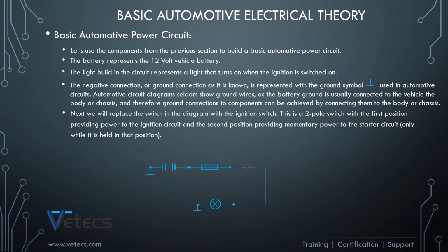Next, we will replace the switch in the diagram with the ignition switch. This is a two-pole switch with the first position providing power to the ignition circuit and the second position providing momentary power to the starter circuit, only while it is held in that position.